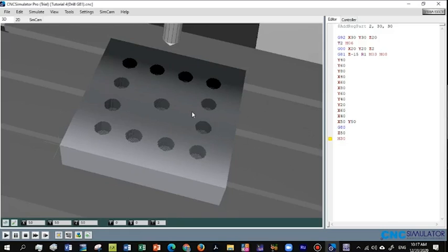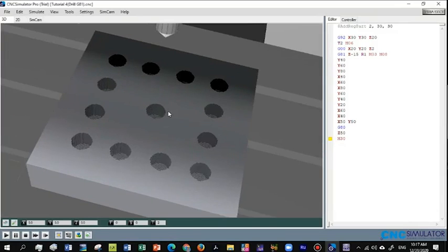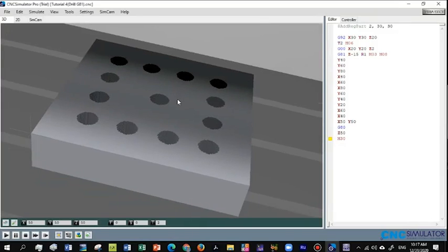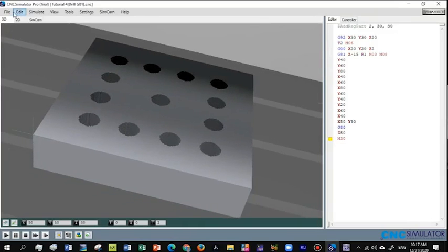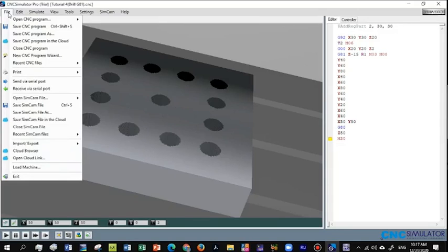And also for the G82 and G83, it will be the same, but you need to define multiple parameters here, like in the case of the peck drill, parameters like Q, IJK, and so on. Usually, if you want the drill to make a deeper hole, in that case you are going to use G83 or G82.